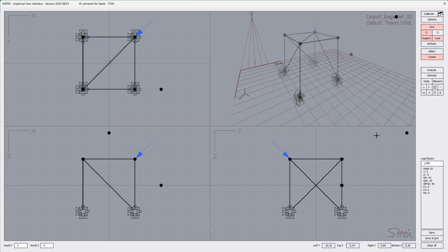The idea is just, again, to be on the safe side, not to create more nodes than necessary. However, of course, it's quite often the case that you would like to create many nodes at once, and then you have to activate this button by a double click. I put a double click on node here, and now you see we are ready to create as many nodes as we would like. Okay. Element, I think it's self-explaining.